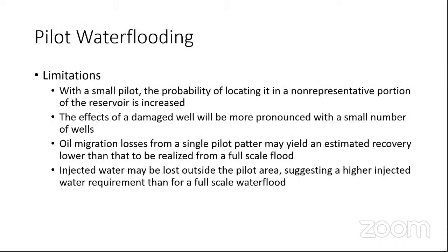Some limitations for pilot water flooding. With a small pilot, the probability of locating it in a non-representative portion of the reservoir is increased. The effects of a damaged well will be more pronounced with a small number of wells. Oil migration losses from a single pilot pattern may lead to an estimated recovery lower than that to be realized for a full-scale flood. Injected water may be lost outside of the pilot area, suggesting a higher injected water requirement than for full-scale waterfloods.